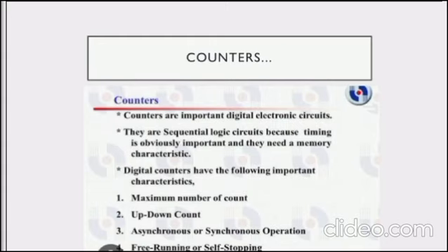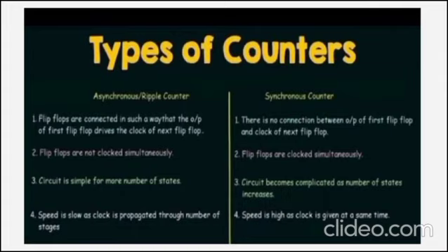The important characteristics. First, maximum number of count. Second, up/down count. Third, synchronous or asynchronous operation. Fourth, free running or self-stopping. Types of counter. Asynchronous or ripple counter.